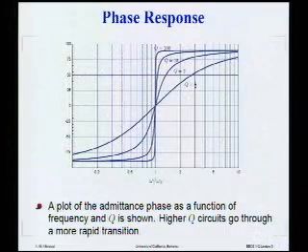And what you find is that the admittance at low frequencies has a phase of minus 90 degrees, and at really high frequencies it has a phase of plus 90 degrees. And it changes smoothly from minus 90 to plus 90 at resonance. Okay? Now the rate of change depends on the quality factor. If you have a small quality factor, it's a pretty smooth change.